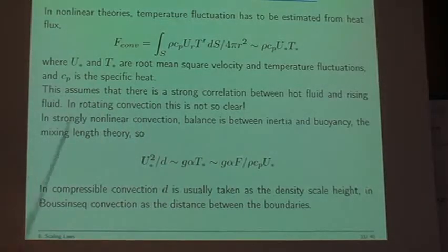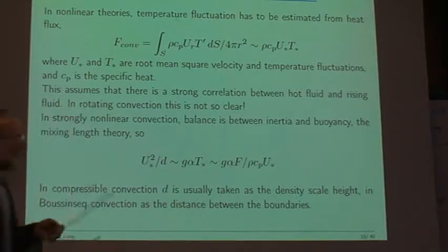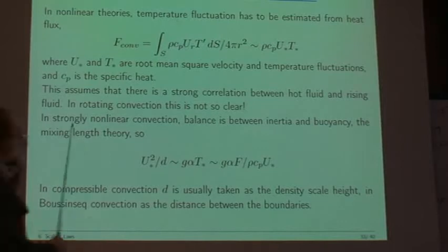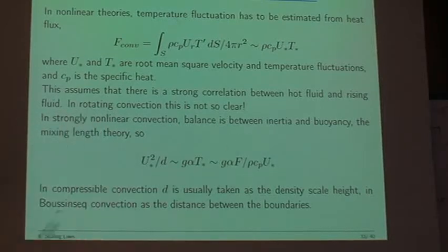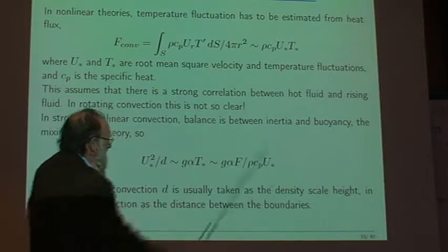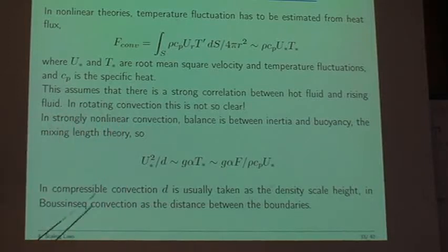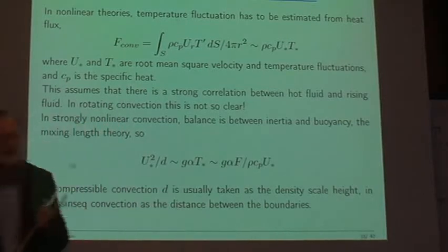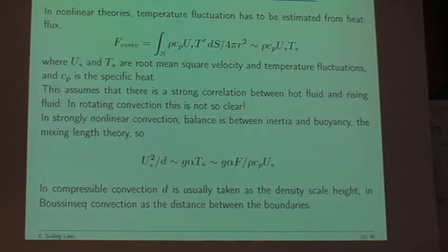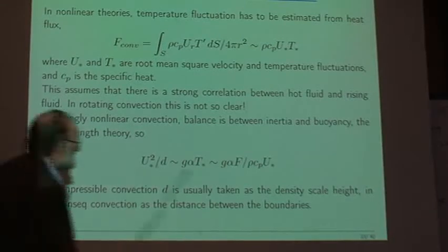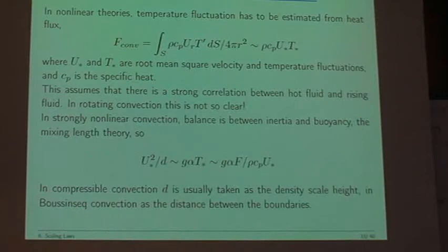And then we've got to start thinking about what forces are going to be important in the equation of motion, because that's crucial to understanding the velocities that they're going to achieve. Now, remember what terms we actually had in all this. I'm going to take out the pressure because it turns out that when we take the curl of these equations, the pressure drops out, and so that suggests that it plays a less important role.